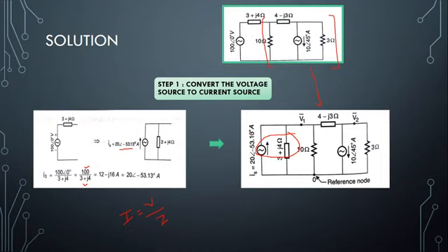Next, what we should do, I need to find out what are the nodes present in my circuit, and we need to define one reference node. So I'm going to take this point, which is similar to ground, as a reference node. If you see, this 10 ohm and this 4 minus j3 ohm meet together, so I've named this common point the voltage point V1.